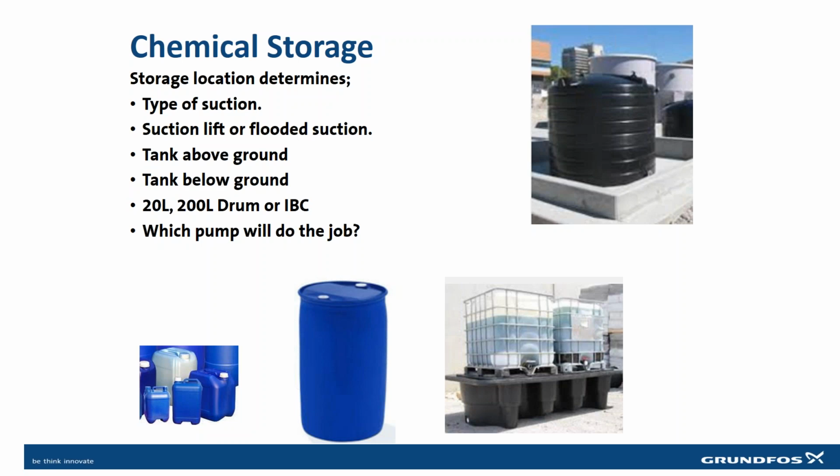The type of chemical storage certainly does determine which pump will do the job. People sort of think about pumps as creating a vacuum to pull the chemical in. The reality is that diaphragm pumps are a pressure pump. They're forcing the chemical out. They're not designed to pull the chemical in. It's only the atmospheric pressure that's pushing the chemical into the pump on the suction stroke. So if we've got a suction lift of 3 or 4 meters, we might need a special pump that's going to give us that type of suction lift. It's all important information to size or determine the correct dosing pump.